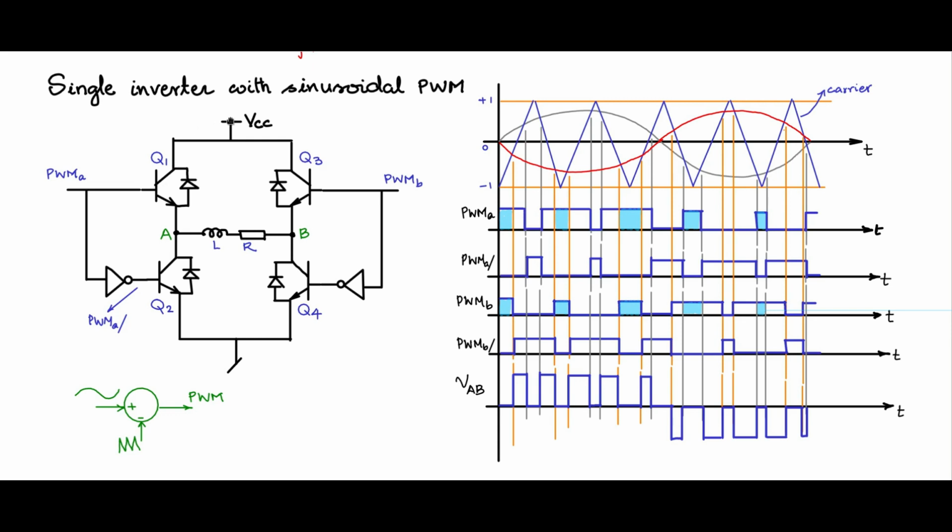During that time, there will be a shoot through directly from VCC through Q1, Q2 to the ground. So that is called the shoot through current. This is not desirable, because that will cause Q1 and Q2 to deteriorate, or you may have to overrate the devices, which is not actually a good thing to do, because it can be very costly. So in order not to have these shoot through current stresses, we provide dead time.